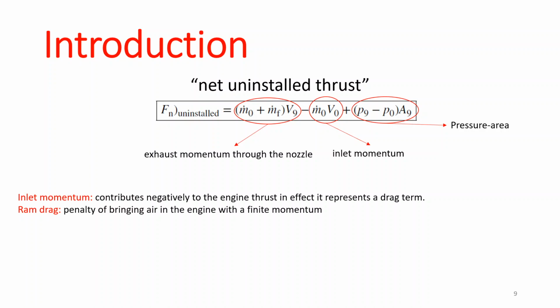Exactly. So essentially, your propeller adds momentum to the air, right? That's the job. So essentially, in effect, it is adding ram drag, right? But at higher altitudes, your air momentum is so low that your propeller cannot add enough momentum to your air. So adding momentum to the air at the inlet is actually very important, right? Although it eventually reduces your thrust, without it there's no way you can have any thrust, right? Does this make sense? In this type of engine, of course.